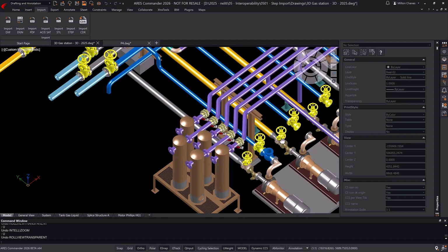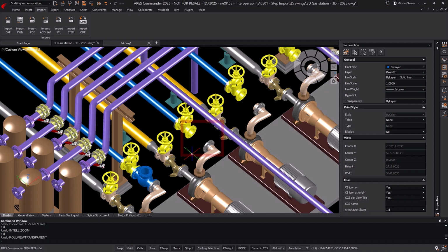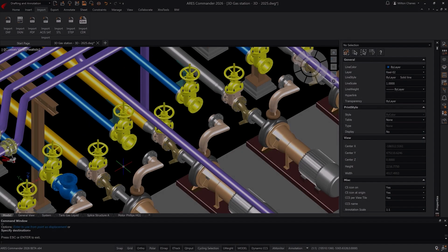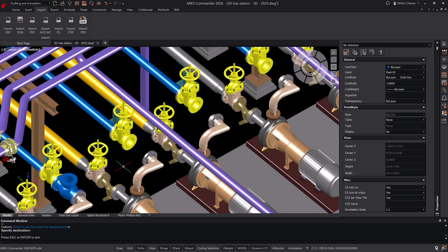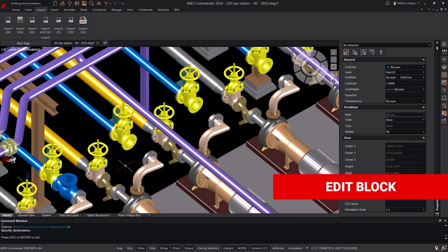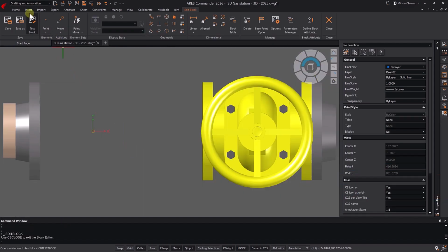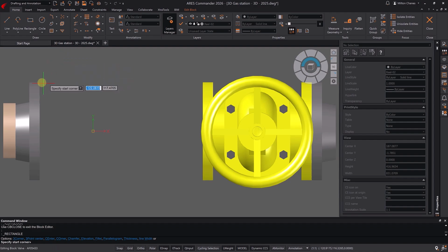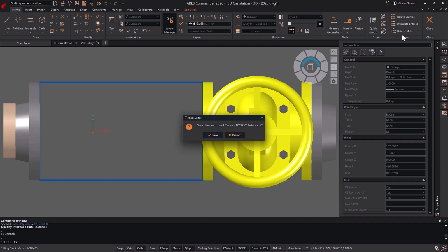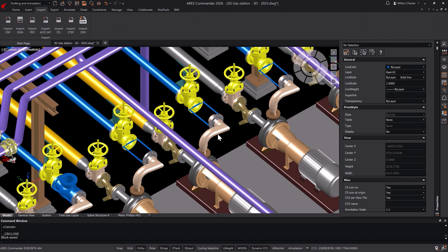For this drawing, the new part must be placed in multiple locations, so we could copy the part several times. But in this example, we are going to demonstrate a more efficient method. The missing piece is part of a larger set, which has been created from a 3D block. Therefore, if we draw an entity here and save our changes, they will be reflected in all instances of this block. In this regard, 3D blocks and 2D blocks operate the same way.